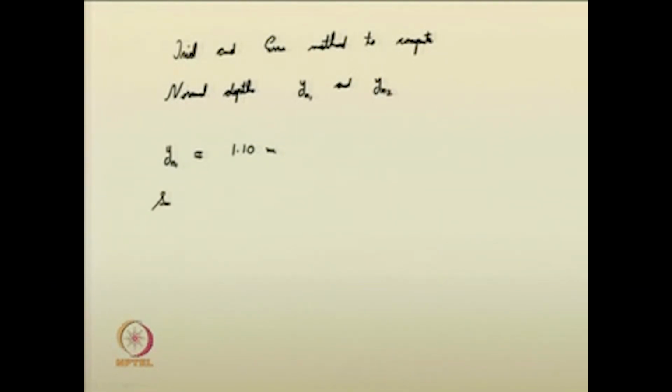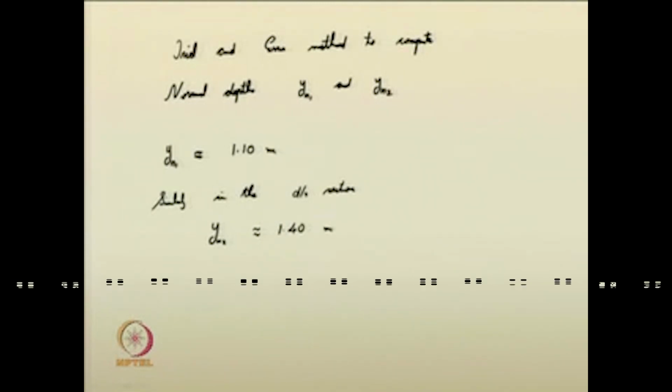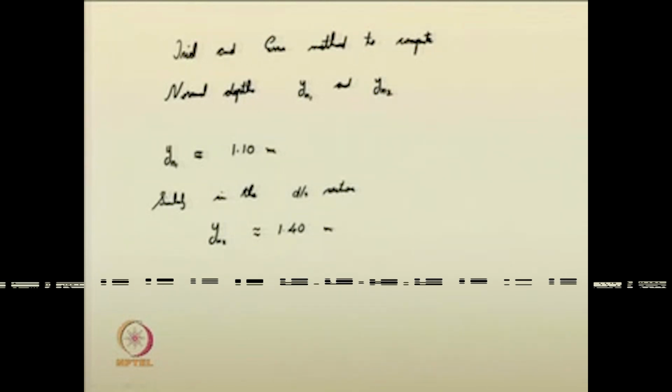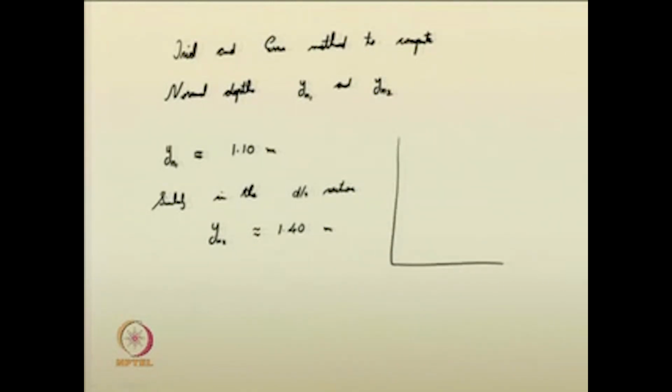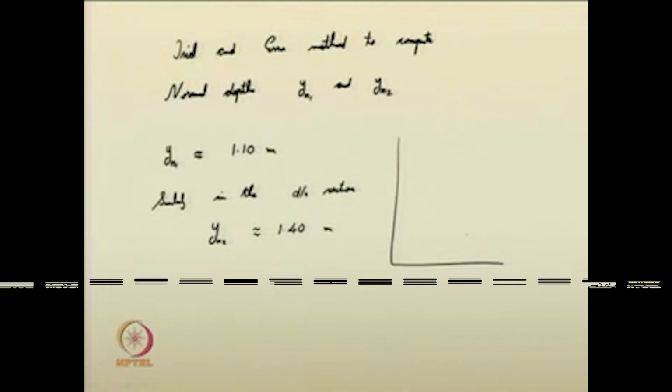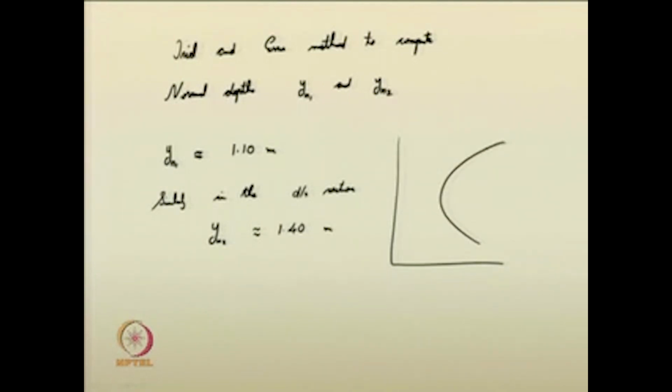Similarly, in the downstream section, yn2 is approximately equal to, by trial and error method, 1.40 meter. Again, one can draw the specific force diagram.